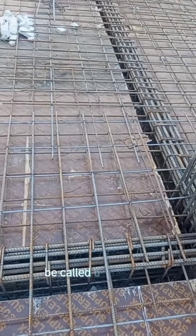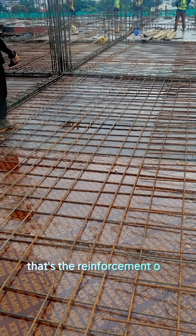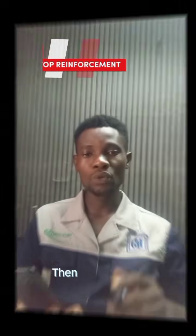Now then we go to the B2. The B2 is the reinforcement on the B1. Now the B2 can also be called bottom top. That is, you can call it B2 or BT, that is bottom top. That is the reinforcement on the top of the B1. Now this reinforcement is a distribution bar in a one-way slab. But in a two-way slab, the B1 and the B2 are main members in a two-way slab. Then we go to the T1.